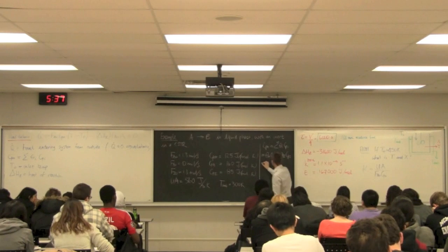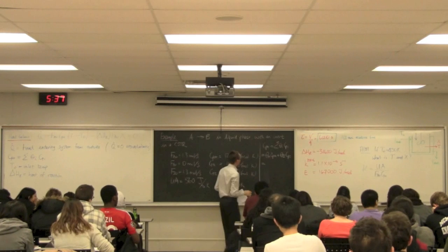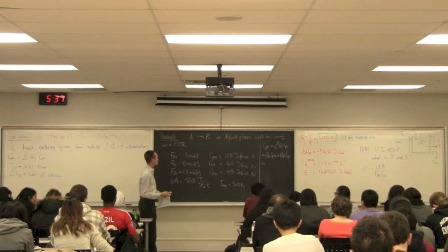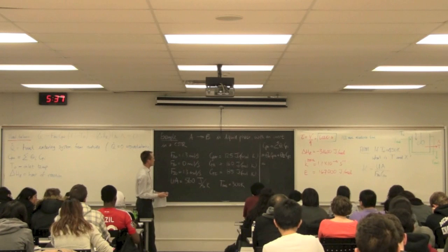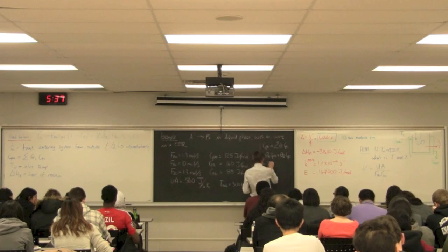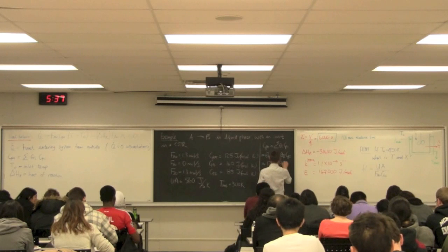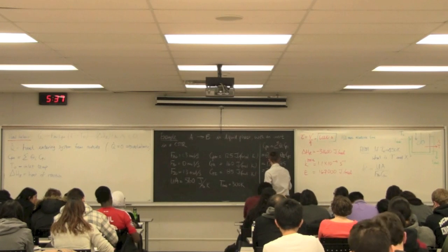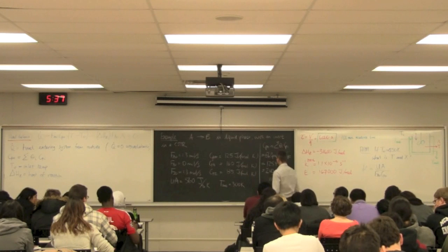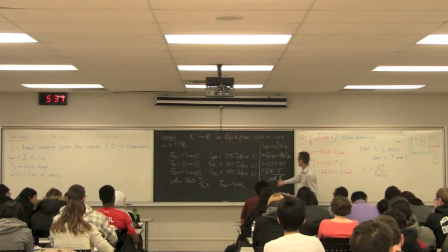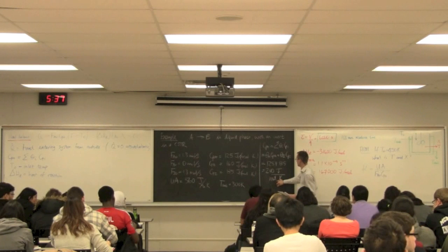So it's simply coincidence that my C_P0 in this case is C_PA plus C_PI, but it's not always the case. It's just coincidence that the thetas are 1 in this particular instance. So C_PA plus 125 plus 85 gives me 210 joules per mole Kelvin. Joules per mole of what? Per mole of my basis species reaction, so joules per mole of A.